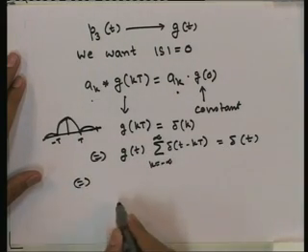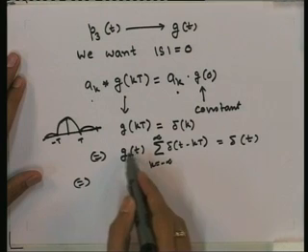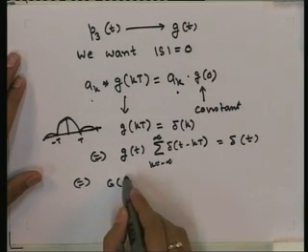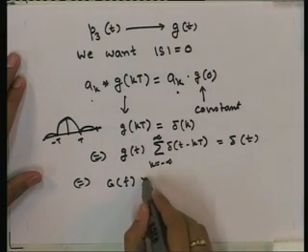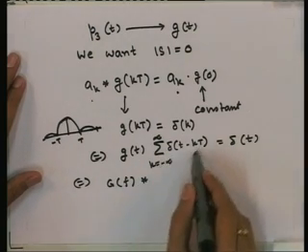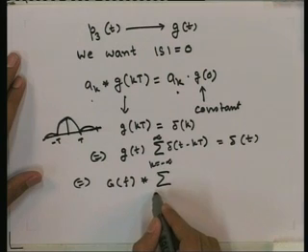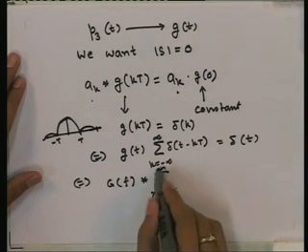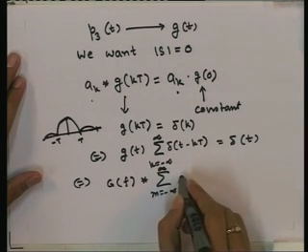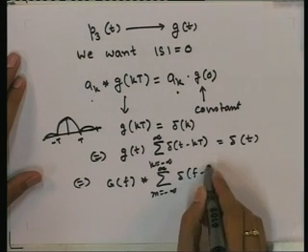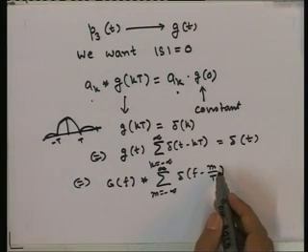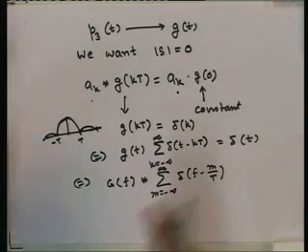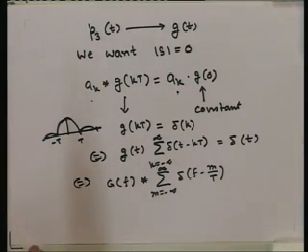Now if we take the Fourier transform, what is the Fourier transform of this? It is G(f), and this is a product, so product will be convolution when we take the Fourier transform. And what is the Fourier transform of this? It is known to be again delta(f - m/T). So there are deltas spaced 1/T apart. 1/T is a frequency, T is a time.